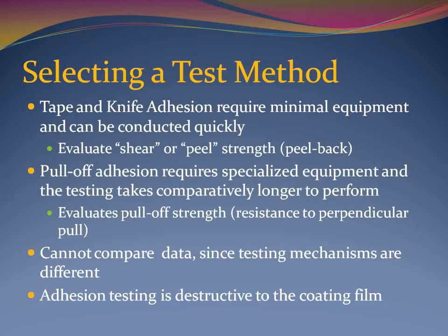Non-destructive pull-off adhesion testing can be performed by applying the load up to but not exceeding the contract specified tensile force. The load can be decreased and the fixture left on the coated surface, provided the contract permits this practice.